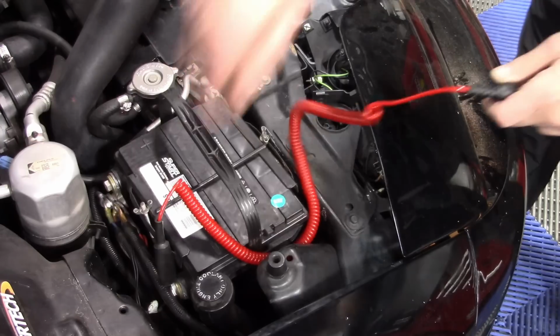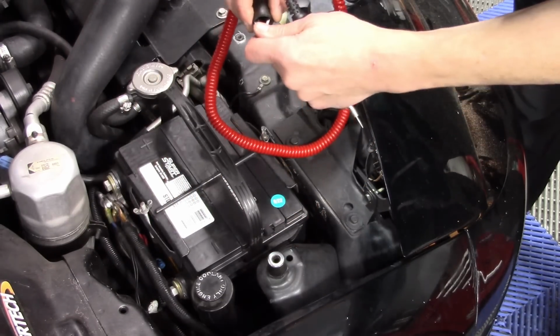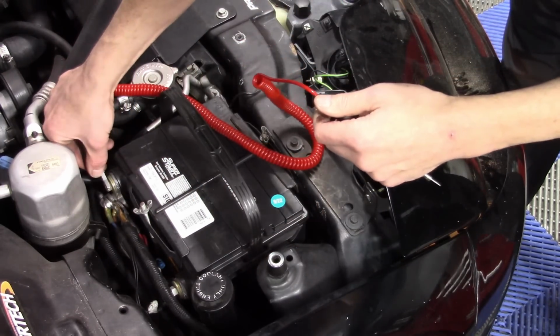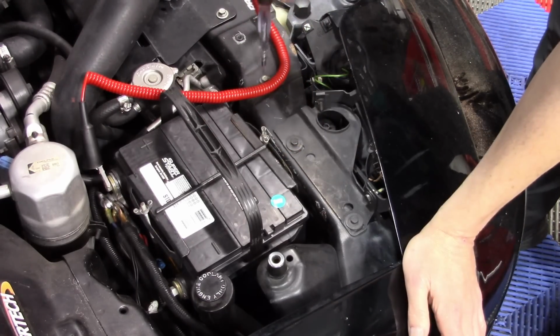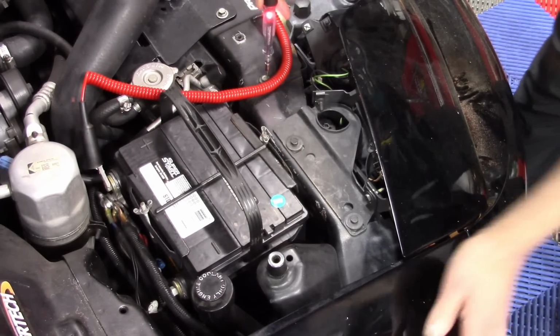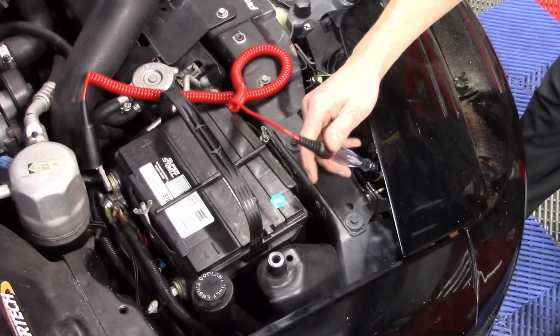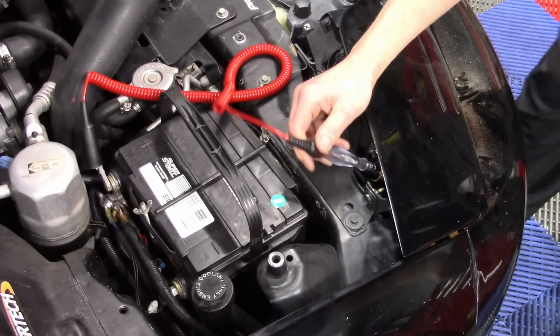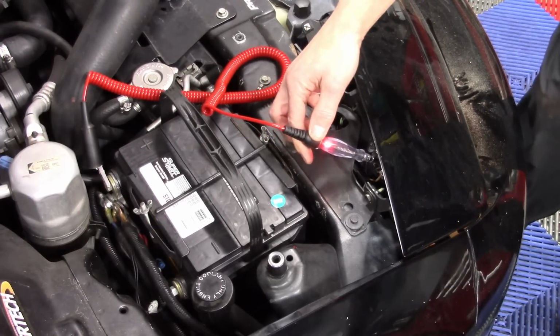All right? Can also reverse that. I could take my test light and make a ground finder out of it. Take my test light, put it on battery positive. Now, anytime my test light finds a ground, it's going to light up. Let's go over to our positive wire. We see there's no ground there because that's a power. Test light does not light up, but if I go over to the ground, we see it lights up.